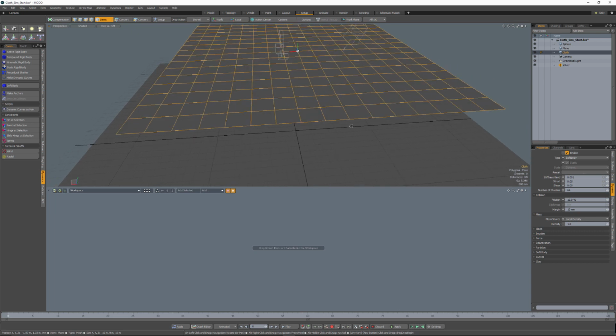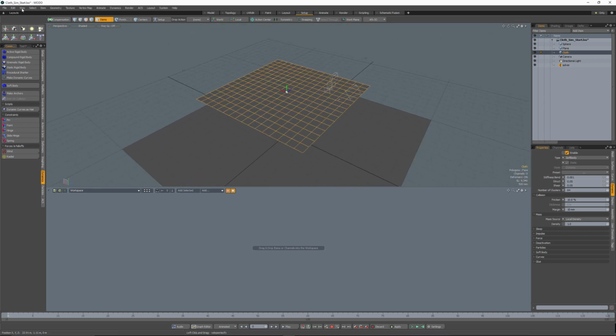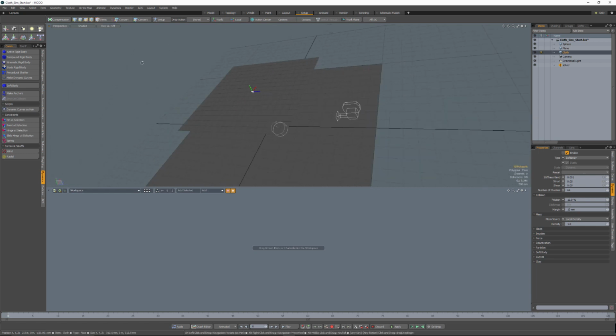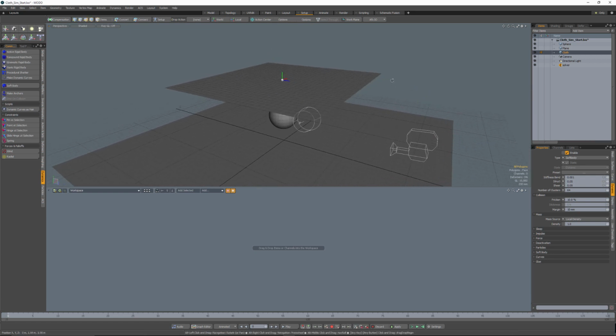So let's go ahead and stop our playback by hitting escape. And now what I'm going to do is move over to Polygon Mode, move over to this cloth item here, and press Shift D to subdivide this. I want to make sure I use faceted because that's just going to divide each quad into 4 quads. It's not going to try to round anything, so we'll do that. And now we've essentially doubled our resolution in each direction. Okay, so let's go ahead and hit play again.